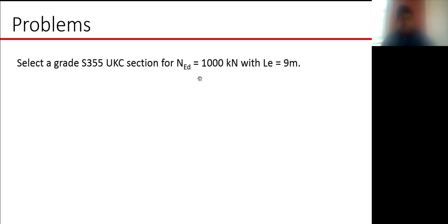NEd is the design effect. N stands for axial load. So there is an axial load of 1000 kilonewton acting on an S355 channel section, and it has an effective length of 9 meters. We need to choose an appropriate section that can handle this load.